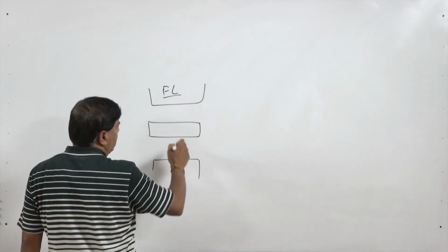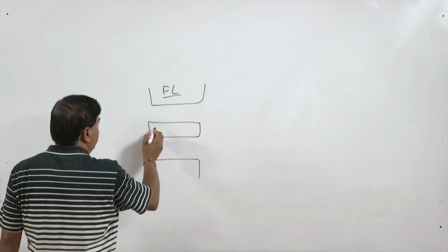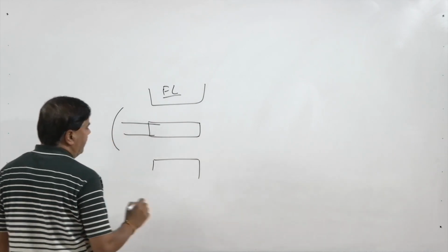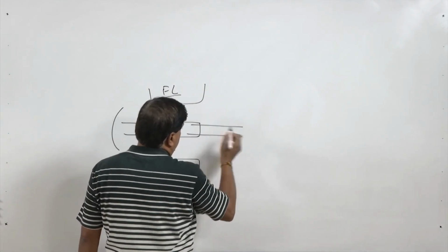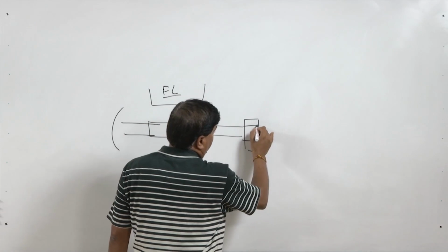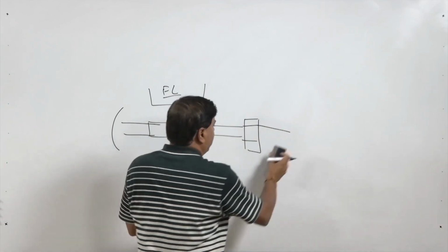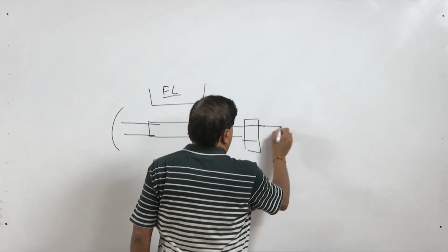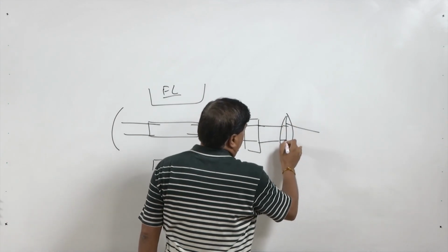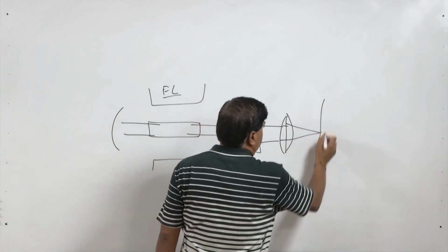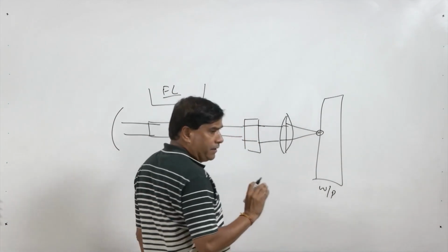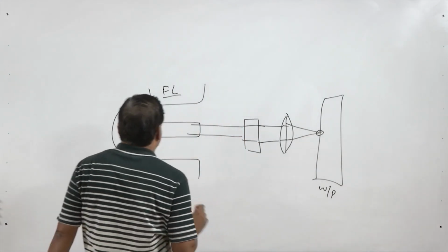After the excitation the laser radiations are emitted, then they are reflected back using suitable reflectors and brought to parallel, then through the lens they are focused at the desired point, and this point becomes the workpiece.